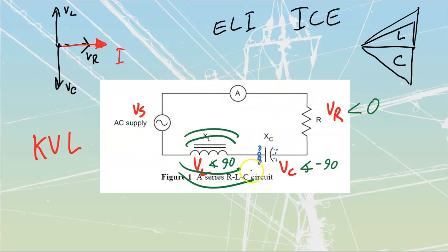When this thing needs current to fill up its coulombs, it's able to take it from the collapsing supply it has over here, these lines of magnetic flux. And when this one needs current to build, to try and maintain that, it can take some from there instead of having to use all of its magnetic lines of flux. We really just see this cancellation from one to the other.